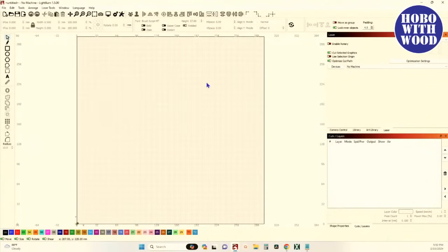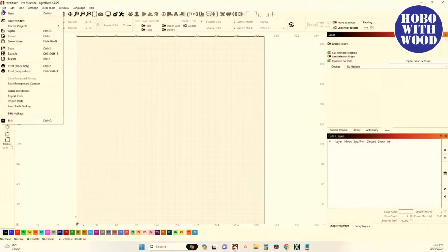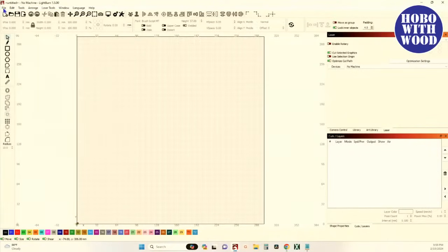One, just FYI, to open up a new window, you can just go to File, New Window. You don't have to do it from the taskbar. But I will warn you, if you set up a new device in one, and then you have another window open, that other window will not get the message that there's a new device configured. And if you close that one first, it will save its prefs and it will wipe out the other one. Okay, so that's what happened. I was not aware of that. Will the other one's prefs be saved in a backup then, though? Yes. Okay. So you could get it back if you wanted to. So go real quick. Go to File.